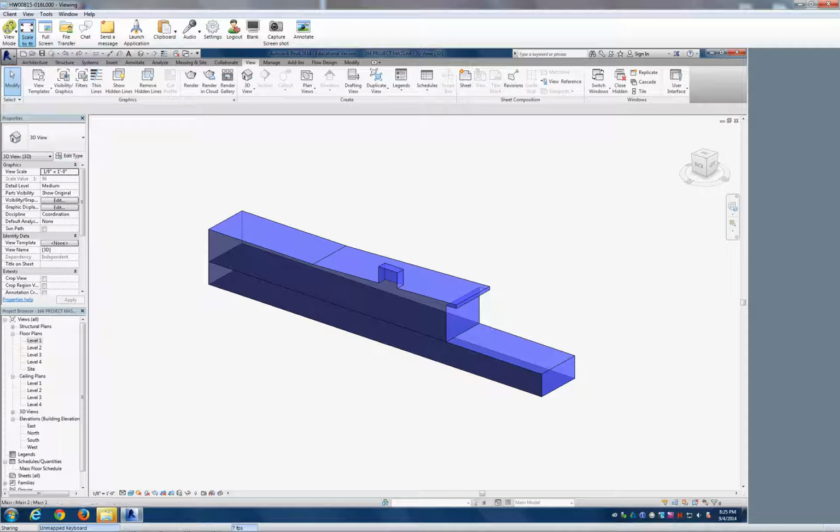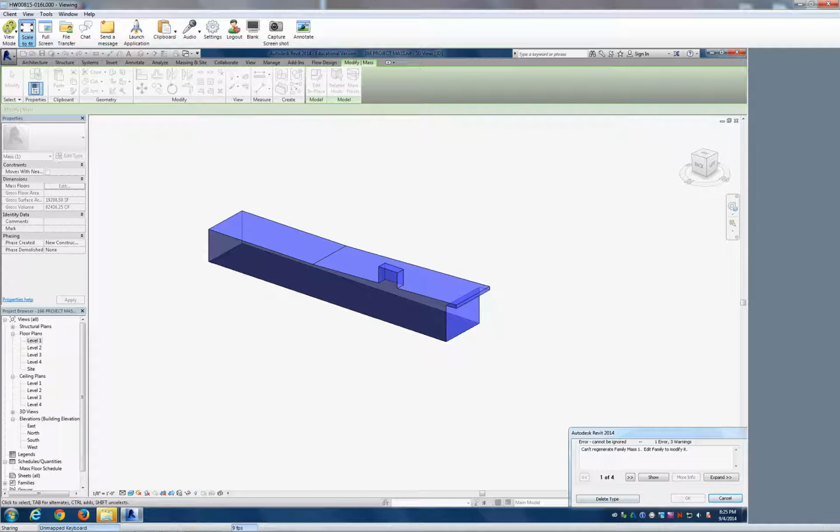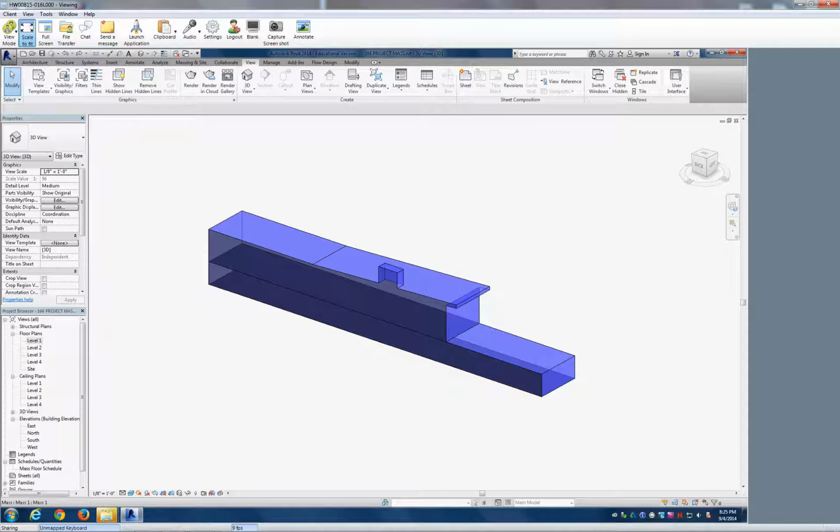It gets problematic because reference planes sometimes just take the last part that you extruded. So this is the downfall of locking something. Probably don't lock it to reference planes unless you know it's done. The reason why is actually, never lock it to reference planes. It's a good idea, because what's happening here is I'm locked to that reference plane, but when I move the reference plane, it's just moving the bottom line. The top extrusion line stays. It's not the end of the world.